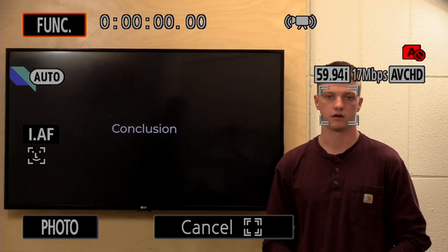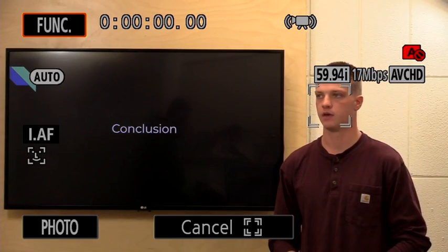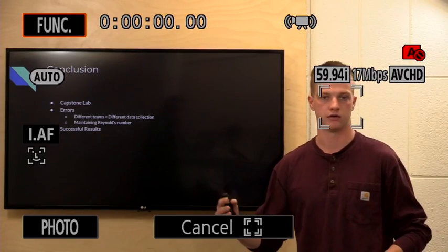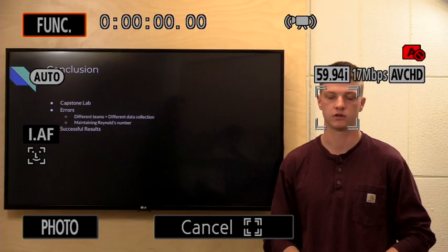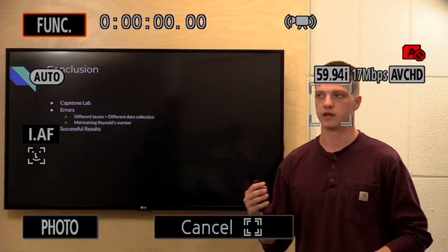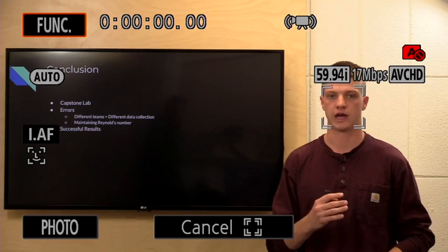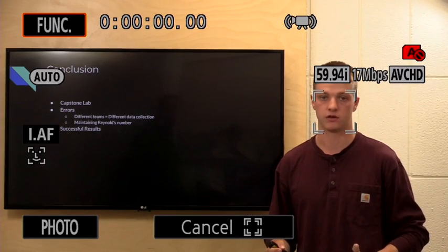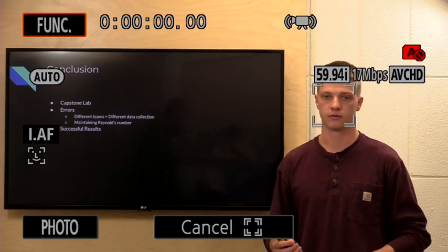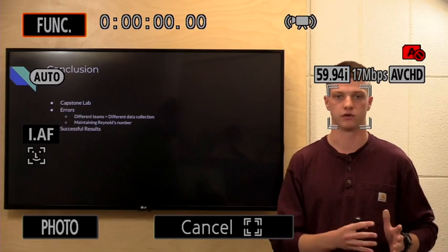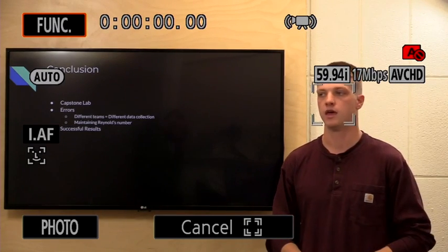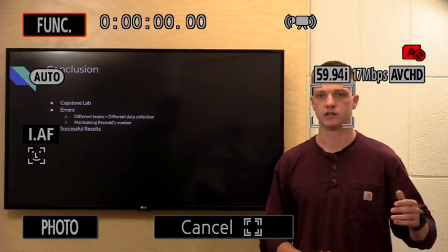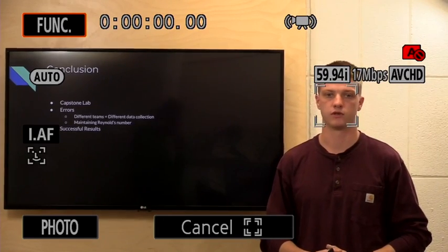Hi, my name is Luke Baer, and we'll be going over the conclusion of this lab experiment. And so, to conclude, this lab was basically a capstone of our entire aerospace portion of the laboratory section. And by being a capstone, we had to, in earlier labs, set up to this one. And that includes calibrating the venturi factor of the wind tunnel that we had, calibrating the pressure transducer, which would convert our pressure to speed in the wind tunnel. And then we also had to calibrate the hot wire, which would give us the velocity down towards the finishing portion of the wind tunnel.